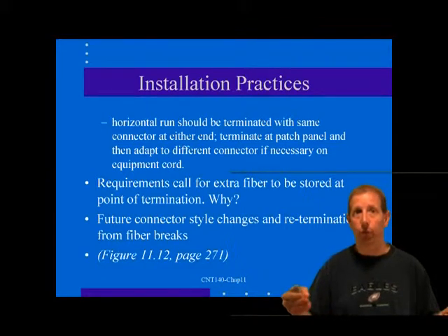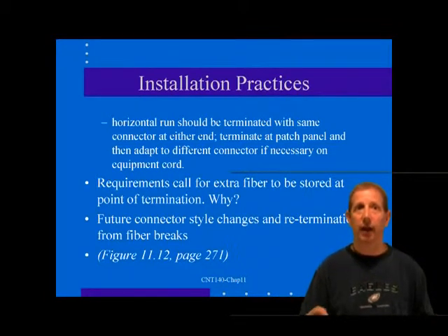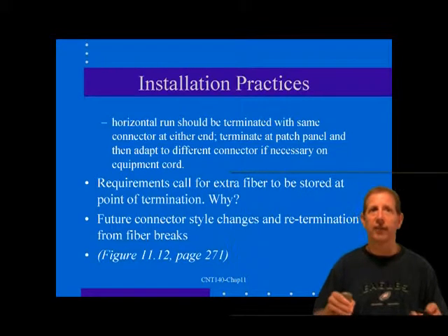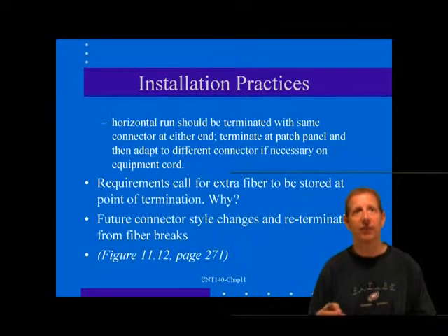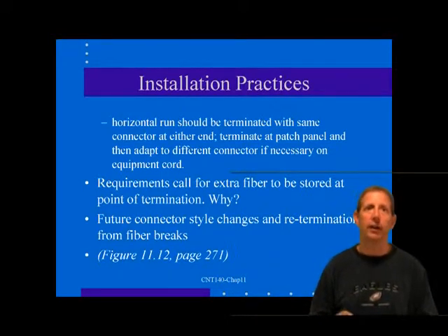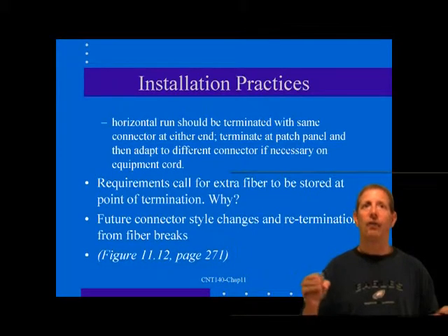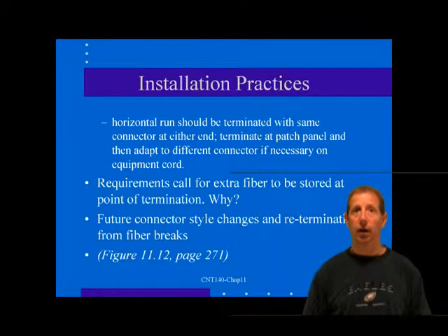This brings some basic rules of optics into play. First, if this break is not precisely 90 degrees, the light will exit the fiber at a slight angle. And second, the break is never exactly 90 degrees. The cure is to place the fiber end into a matching fluid so that the off-axis break has virtually no effect, in a so-called field termination connector.